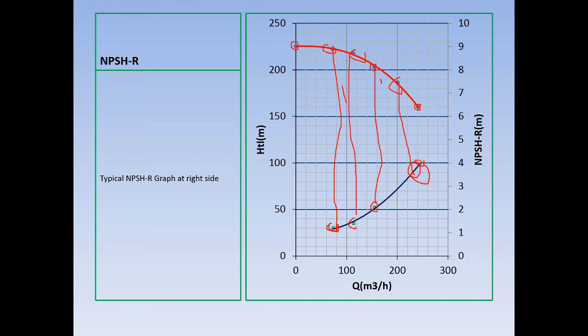Okay, so that is why it's a climb. But the climb is not linear. The climb is a polynomial, so you have to be careful on this. Let's say your design point is here. You're operating here, and suddenly somebody opens the valve, or you want to increase your plant capacity into here. Be careful. Suddenly NPSH required increases a lot.